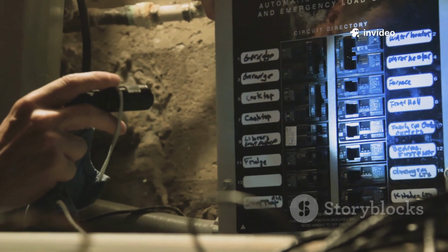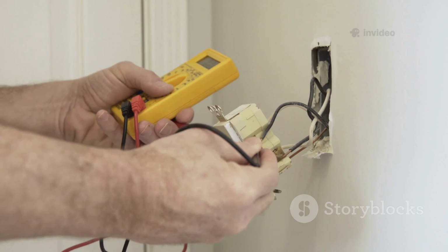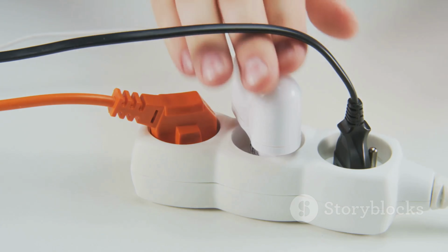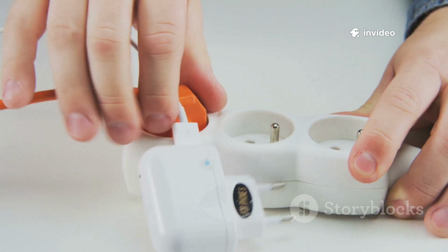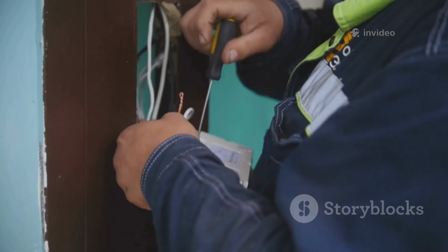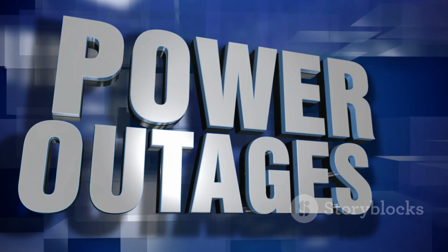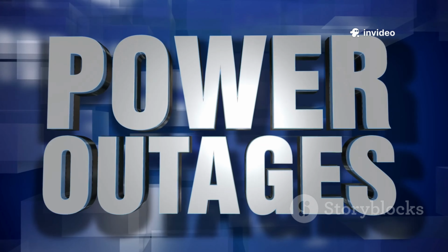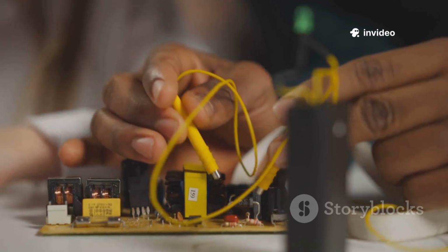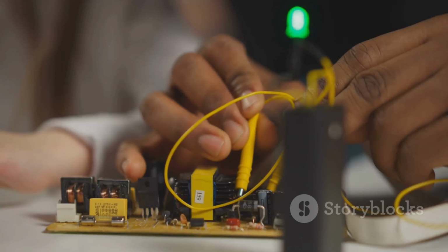Household electrical wiring is a perfect real-world example of parallel circuits in action. Each outlet receives the full voltage from the main power supply, ensuring consistent operation of your devices. And because they're wired in parallel, unplugging one electrical device doesn't affect the operation of any of the others. Now imagine for a moment if your entire house were wired in a series configuration instead of parallel. Unplugging just one single thing would immediately shut down the entire electrical system, plunging your house into darkness. Thankfully, parallel circuits are the standard, allowing everything to keep running smoothly and independently of each other.